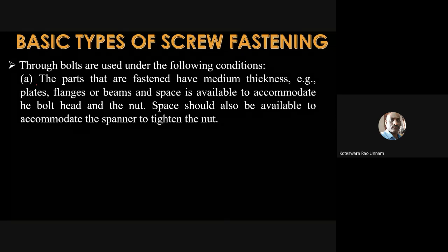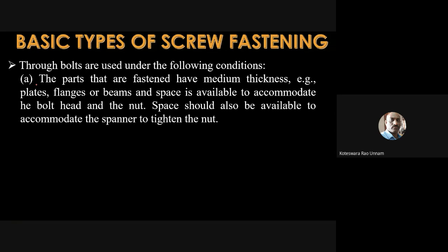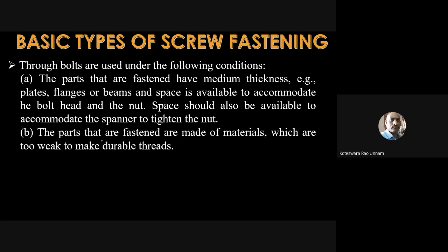If the thickness of the plate is very small and you drill a hole in it, it will make the plate much weaker. That's why in the case of lesser thickness plates, we won't use screw bolts. We'll go for cap screws or studs. So, this is one condition where you can use screw bolts.